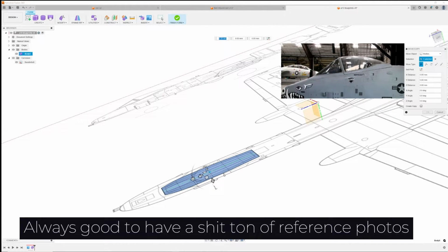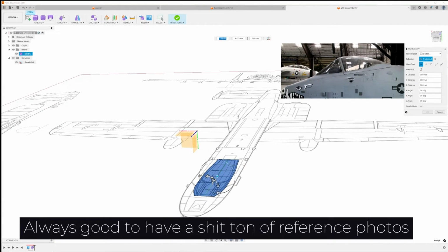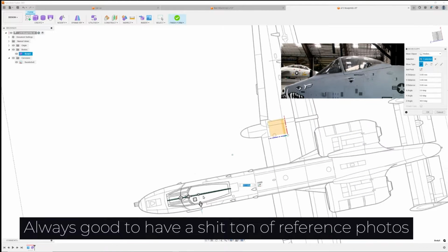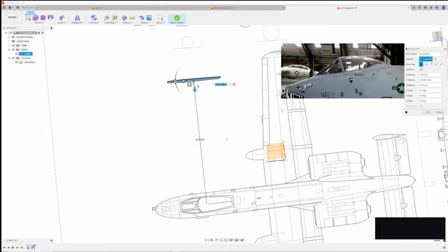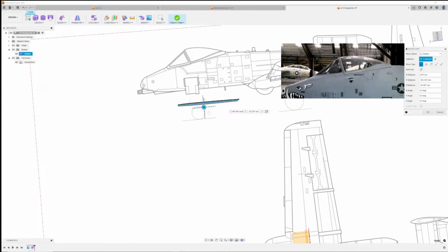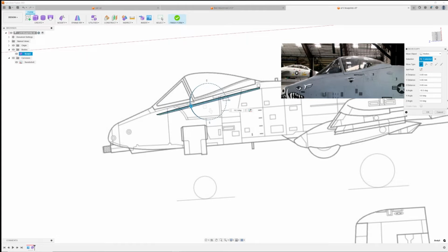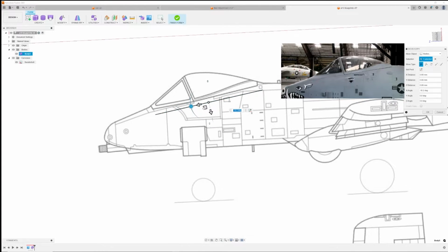At this point, move the plane to the profile view of the plans. Use the Move command by typing M or right-click, then select Move. When selecting the Move pivot point, select the center of the plane you inserted. This will make it easier to keep the plane centered when moving to the profile view. Please note, you can skip a step by inserting the plane directly to the profile view if you wish. I only started with the top view for a bit of scaling.